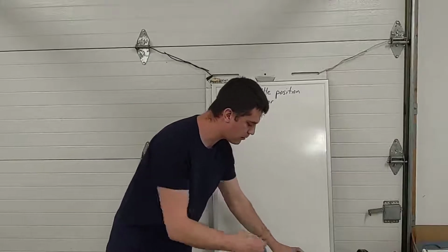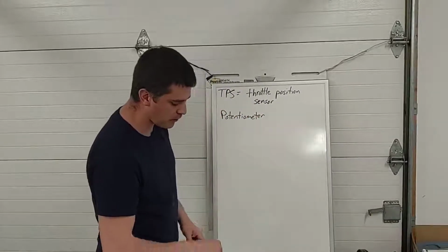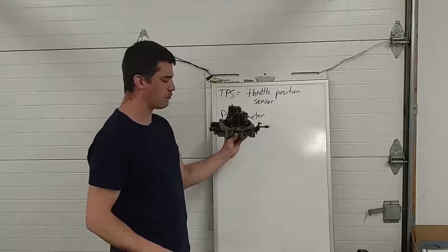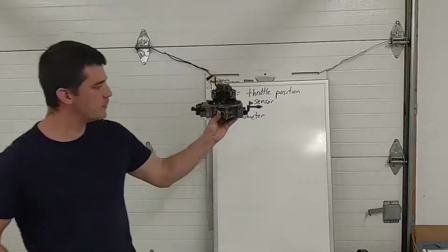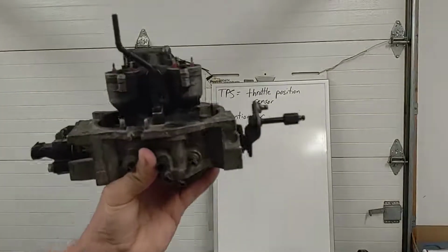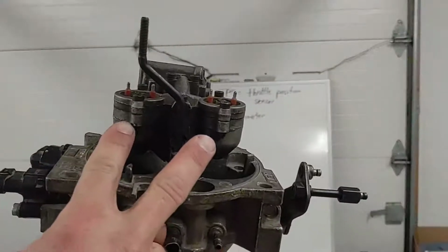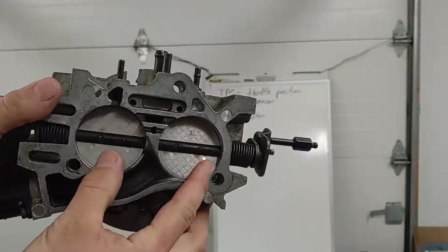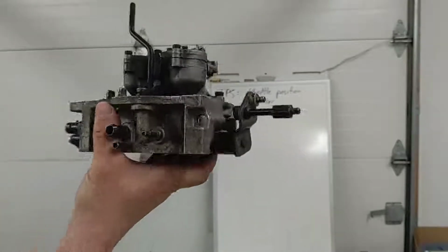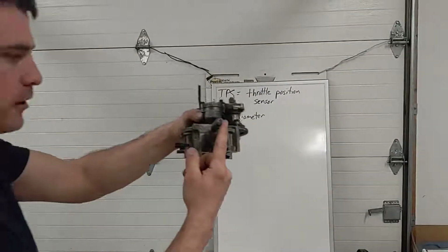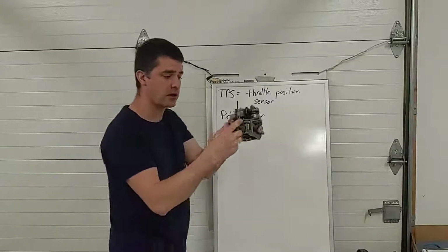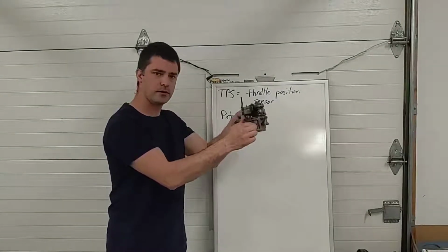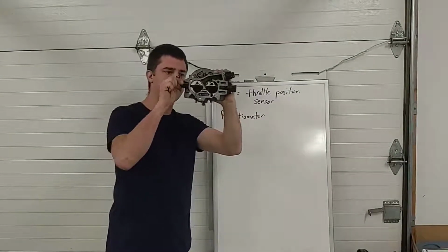When we got away from carburetors, you might remember that one of our earlier fuel injection systems was this throttle body injection. So up in the top of this throttle, we have a couple of injectors that are going to squirt right down into the engine, right over our throttle plates. And naturally, this being an older system, there was still a throttle lever, there was still a throttle cable that connected your foot to this throttle body.